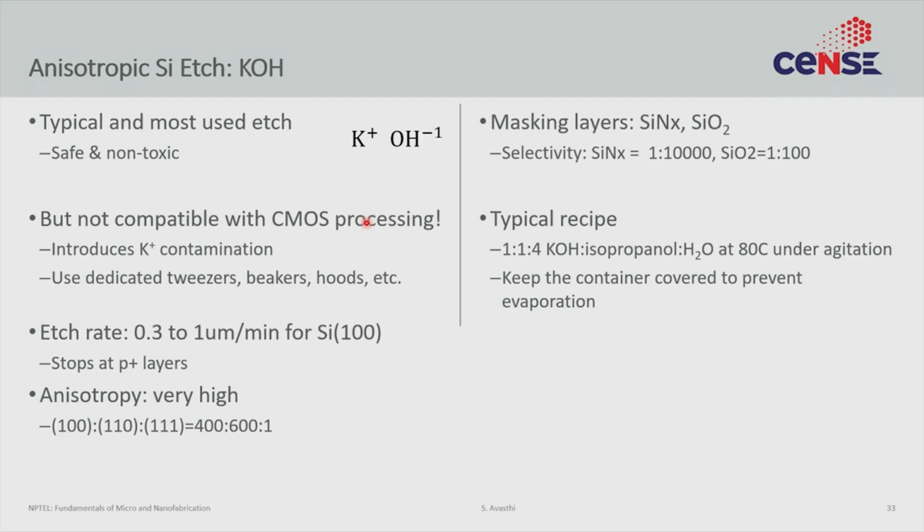When we are doing cleaning, we talk so much about how to prevent alkali metal contamination, how to prevent sodium contamination, how to prevent potassium contamination, how sweat is bad, you should never touch the wafer, etc. The ITRS requirement was a very low amount of sodium and potassium, and all of that discussion, right? And here we are using a chemical that explicitly has potassium contamination, which is why this process is actually not compatible with CMOS. CMOS is what Intel does. They would never allow this process inside their fab. But for MEMS fabs, where they are not interested in electronic devices, or at least electronic devices of the caliber that Intel makes, they are okay with use of potassium hydroxide.